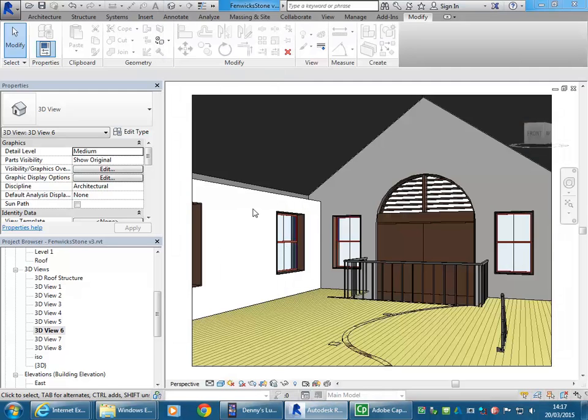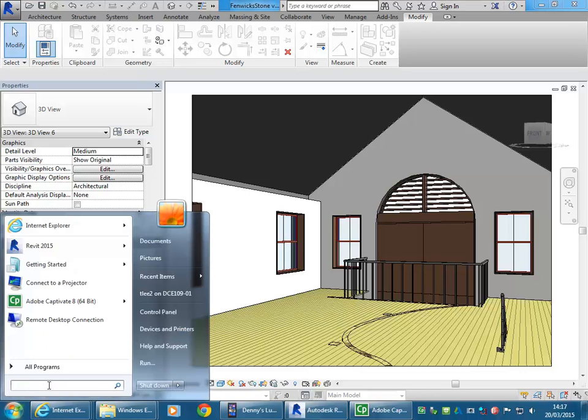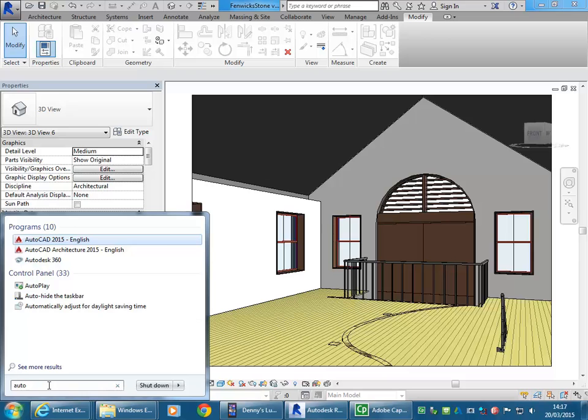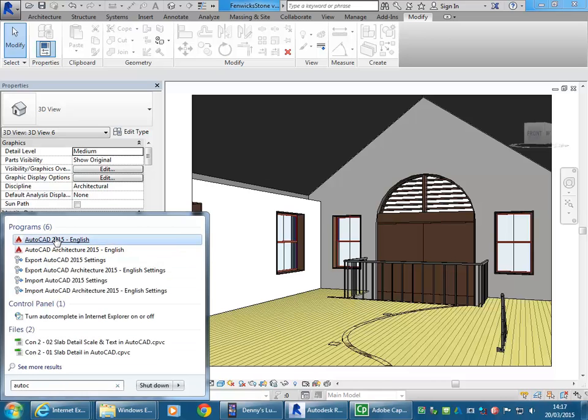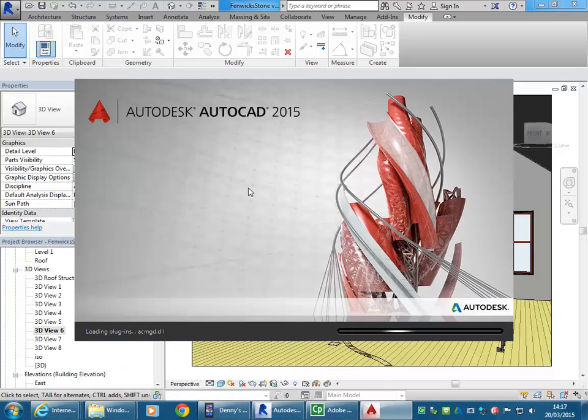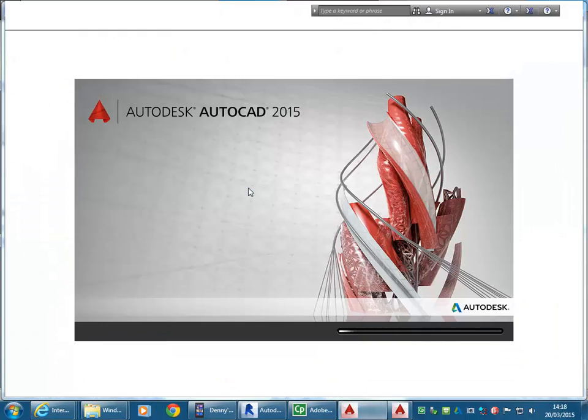And so to have a look at that in Revit, I can bring that into a family file, but like I was saying, with anything you download, to really be able to work with it, you need to know what's there. And because it's an AutoCAD file, it's best to open it in AutoCAD first. Then see how the layers have been set up and other things like that. Otherwise, it's difficult to work with it in Revit.